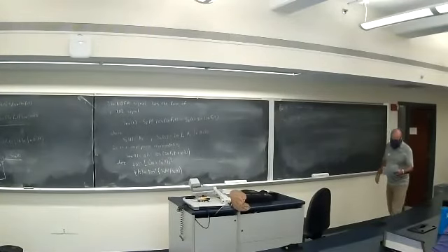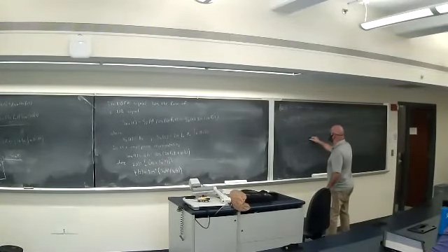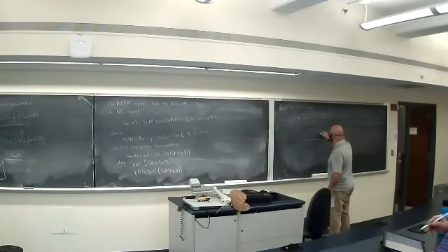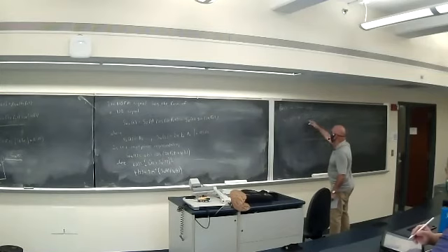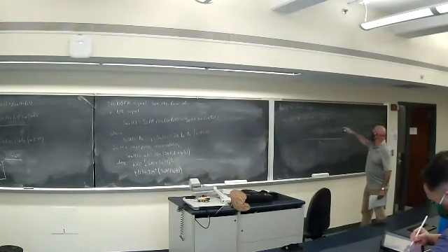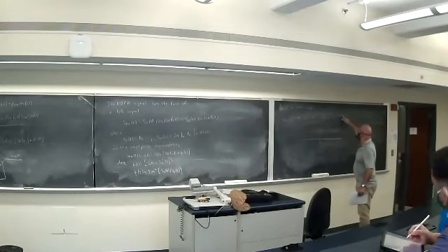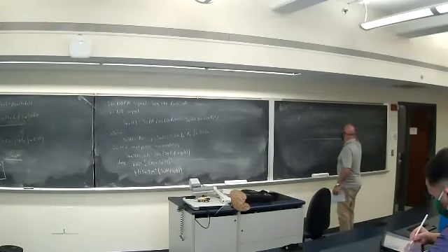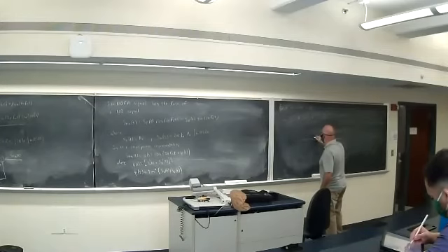Okay. So if we looked at the spectrum of this now, we've got a component at FC that has an amplitude of AC. I'm not drawing the negative frequency components. It would look just like this. We have another impulse at FC plus FM and a third impulse at FC minus FM.